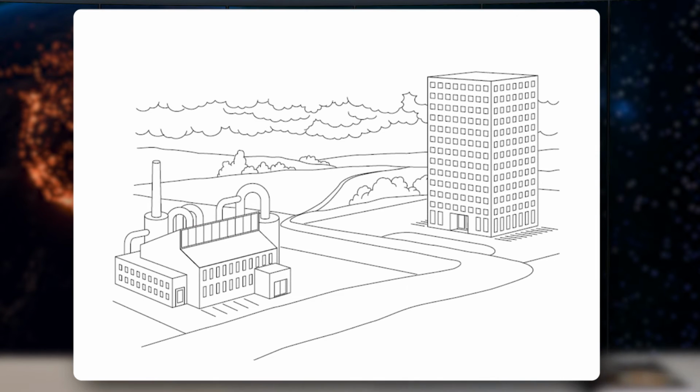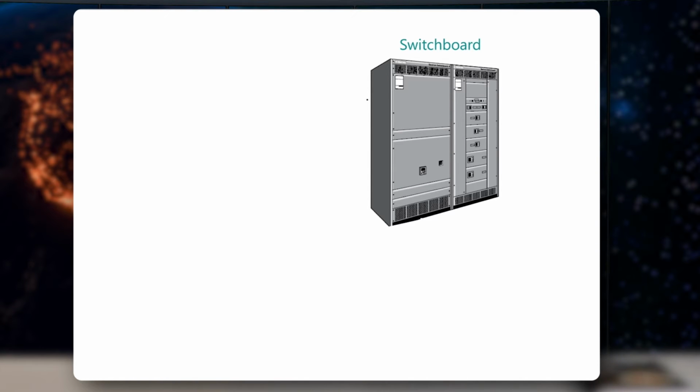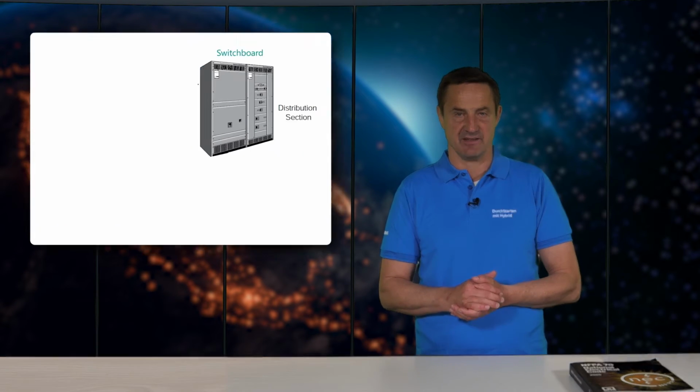If we want to talk now about handling electrical power in large buildings, like office buildings, multi-flat apartments or large industry complexes, panel boards are not suitable to distribute this huge amount of energy in these big buildings. Instead of panel boards, switchboards are used for the electrical power distribution in these big buildings, for dividing a large input electrical power into smaller output currents based on the standard internal busbar system, which connects all the module boxes in the distribution section board, which include disconnect means and overcurrent protection devices.